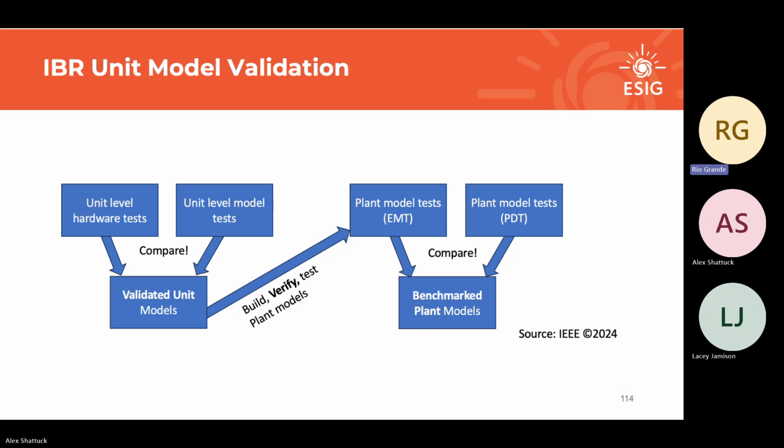a very possible scenario where you're perfectly IEEE 2800 conforming, or perfectly conforming with your utility, like ERCOT's assessment, and you're still grid unstable. So you'll see the flow chart at the end, but it depends on what you want to do and how your risk assessment is. If you want to save some time at the end for probably a restudy, then maybe you just take those base values and pop them in your model and do the test, and then tweak it for a special tuning at the end. But that's also fine, right?